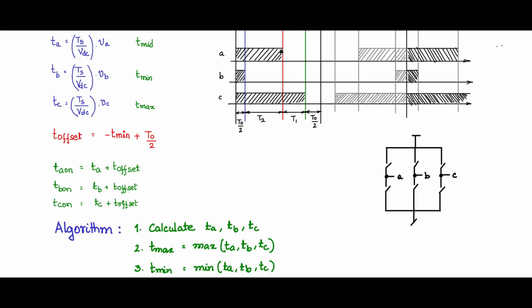At the transition, you will make a small time period called the blanking time period, where both will be off for some time, because this has to account for the rise time and fall time of these practical switches. So that is called the blanking time or the dead time in the literature.